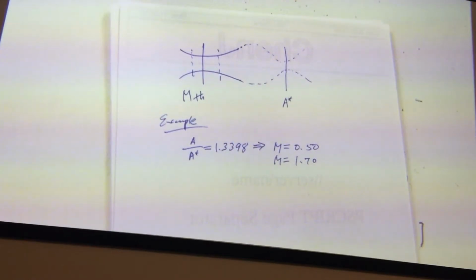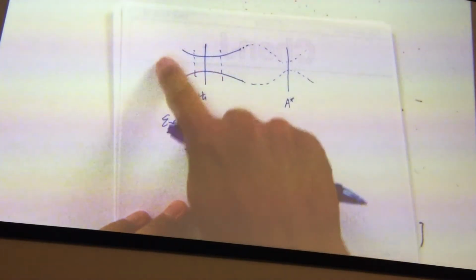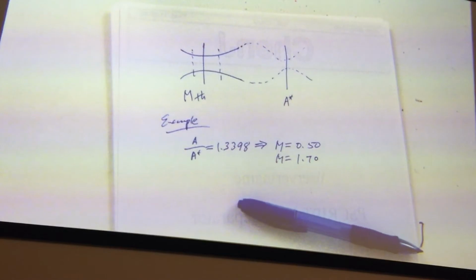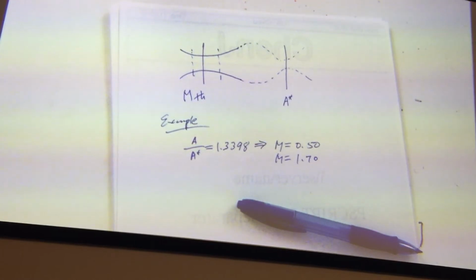If you have a design flow like this, kind of going through a sausage shape, your static pressure will alternately decrease, increase, decrease, increase. So when it increases, you can say, oh, stagnation pressure goes up. Stagnation pressure can only go up if you do work on it. What would be the case?